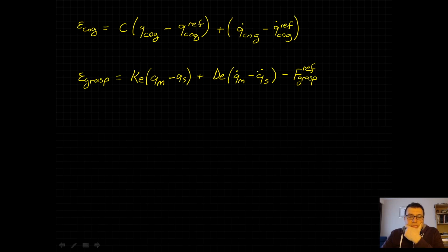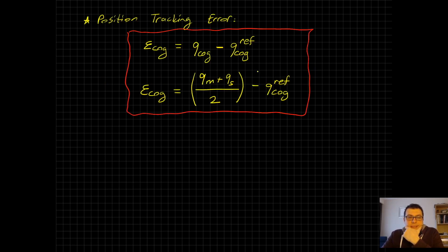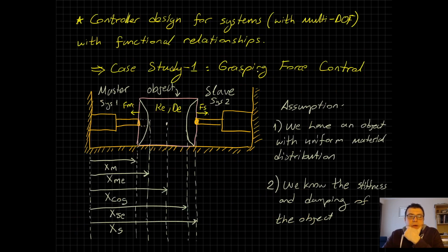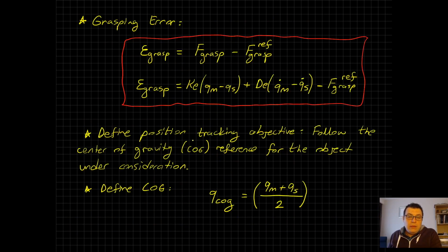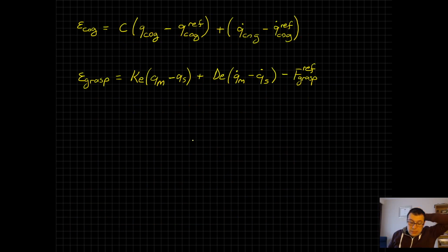I could have forgotten to express one detail, and it's time to express this now, that both of our systems, master system and the slave system, both of them inherently include disturbance observers. So, in the controller derivation, the only task we have to take care of is to formulate the desired accelerations for the master and the slave systems. Before we move on, can we somewhat group these errors and make a formulation for both of them?